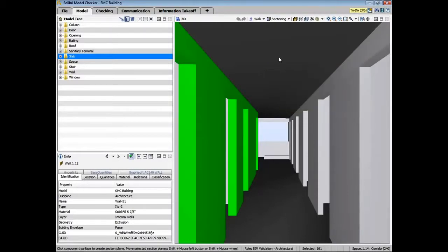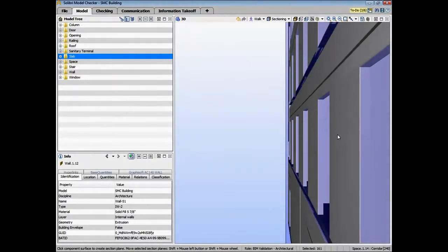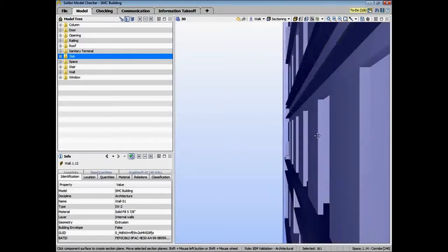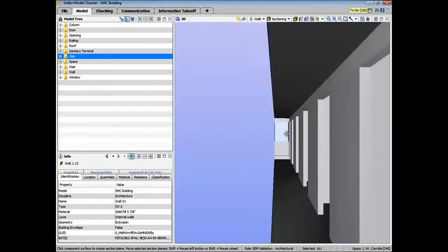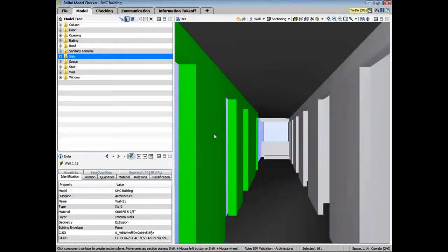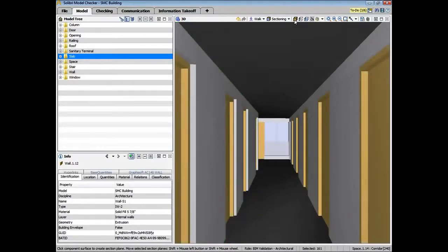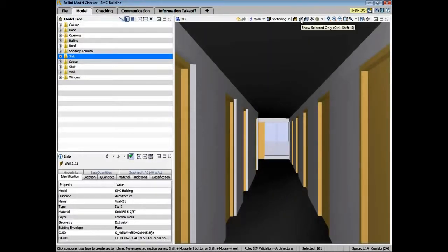Let's use this surface plane to make the section, so we'll switch to a sectioning mode. And you're able to change the sectioning by pushing the shift key. So we, of course, select our original plane that we want to use as the sectioning plane, and then we can adjust those using our mouse and shift buttons. If we again want to go to a completely visible model, we can just choose the Show All button. With Selected Only, you basically get what you have selected earlier, and everything else displays as transparent components.